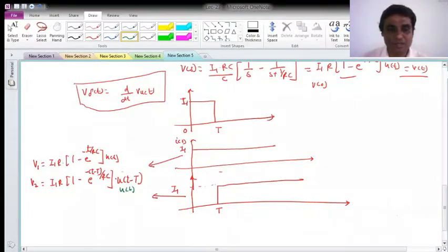But the excitation is the step function applied after shifting u of t by capital T towards right, so the unit step signal starts from capital T. If I write u of t, the output happens at t equal to 0, which is anticipatory, and it will not satisfy causality. That's why it has to be u of t minus capital T.